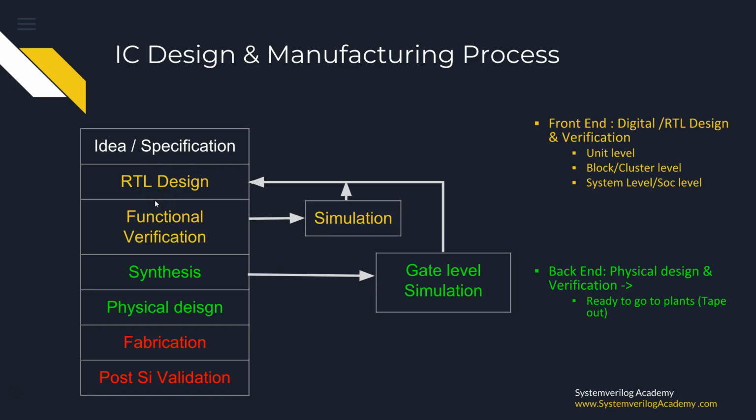The final HDL code is converted to a gate-level circuit using synthesizing tools and will produce a GDS2 formatted photomask that is used to manufacture the IC. These are commonly called the back-end design process. Once the final photomask is taped out, it will be used to manufacture the IC in a foundry. After production, each IC will be validated and finally shipped as a product to the market.